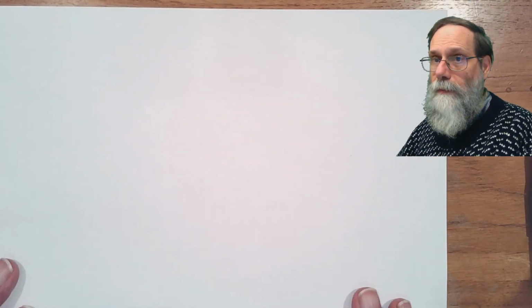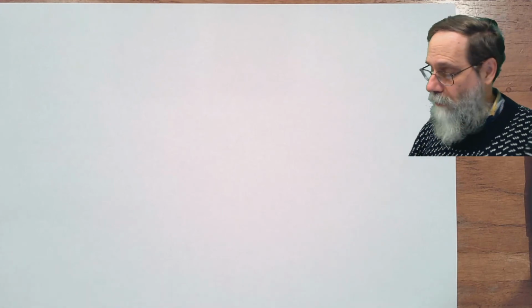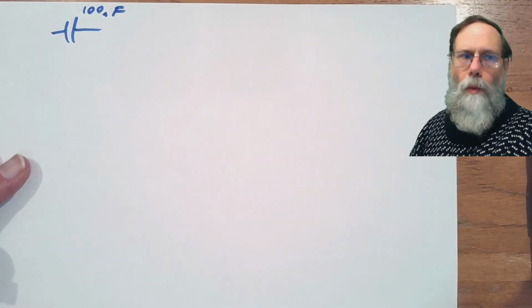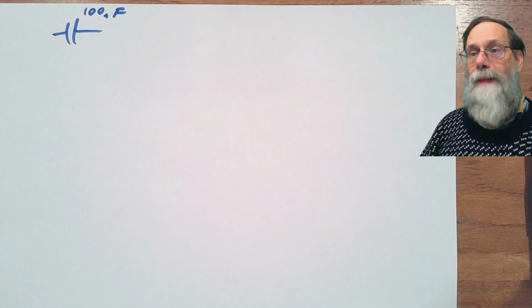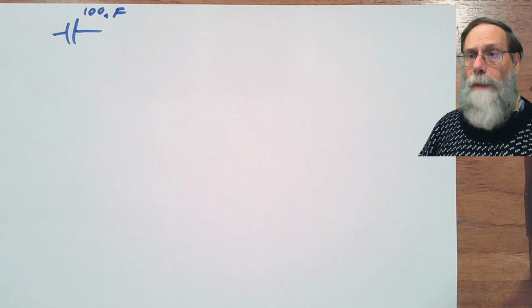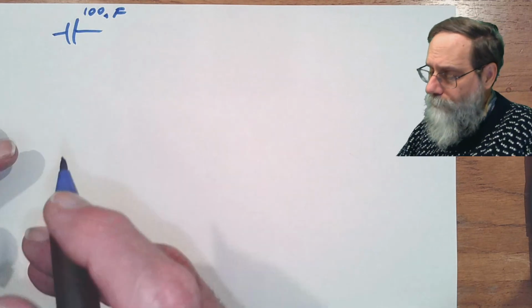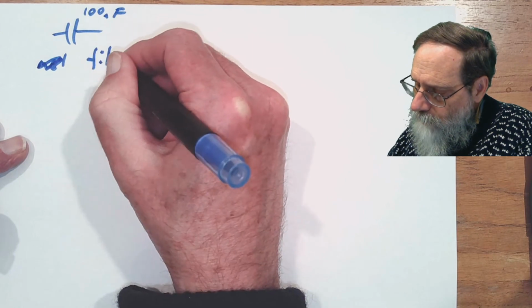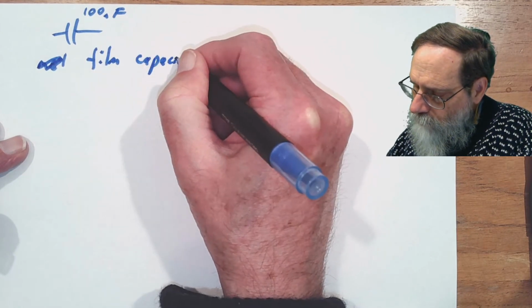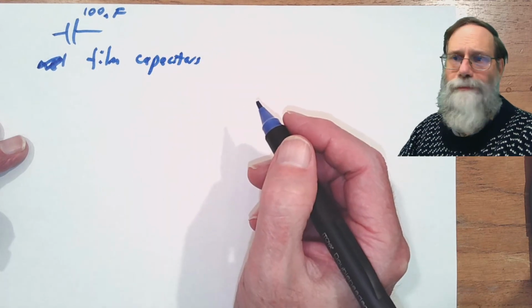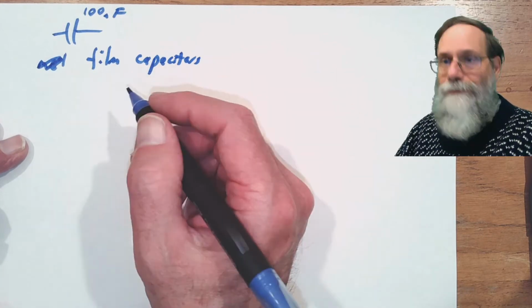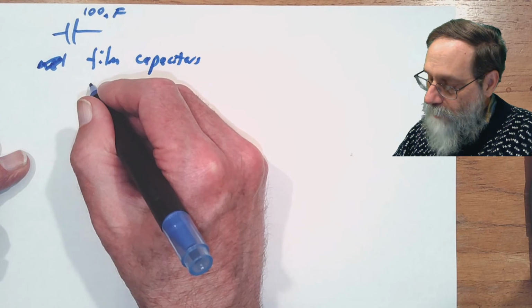Okay. Let's look at capacitors. Again, we may be specifying something like, we want 100 nanofarads. What sort of range do we actually get? And there it depends a lot on what sort of capacitor we're putting in. You can get film capacitors, and these are generally something like a plastic like mylar with a layer of metal plated onto it or coated onto it somehow. You can get ceramic capacitors,